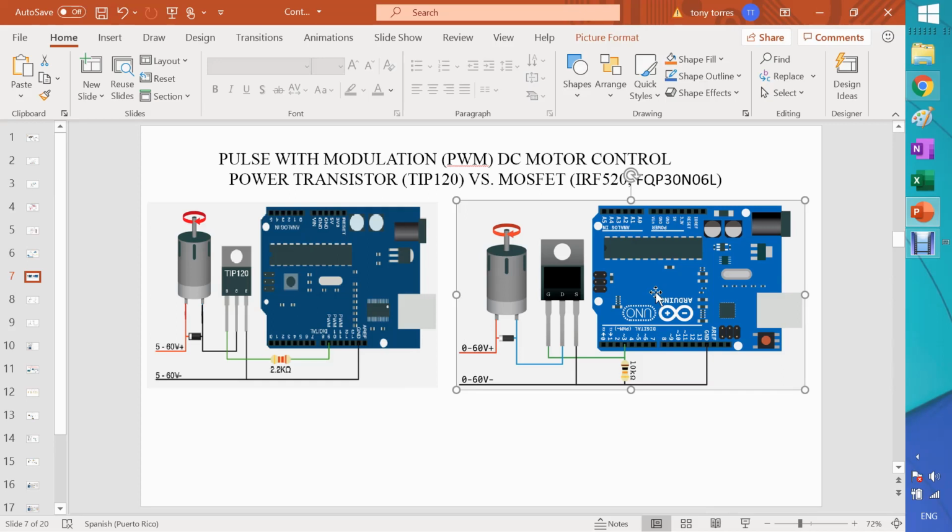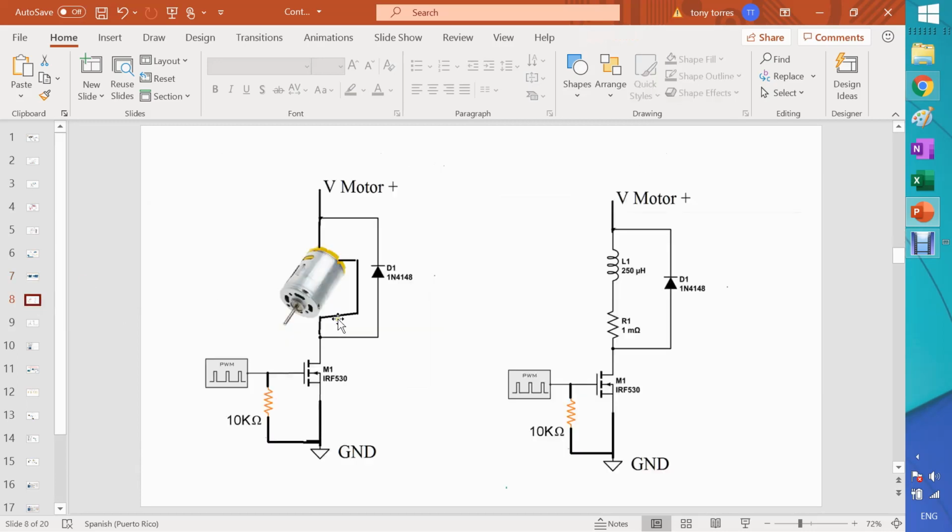I mean, in this case, the duty cycle of the cycle time that I set on the Arduino for controlling the motor was about 20 milliseconds. Okay. So the idea of the MOSFET is right here. You have the MOSFET right here, and then you put a pulse with a duty cycle, whether it's going to be off or it's going to be on, from that 20 milliseconds, this was the width of the on cycle versus the off, and so forth.